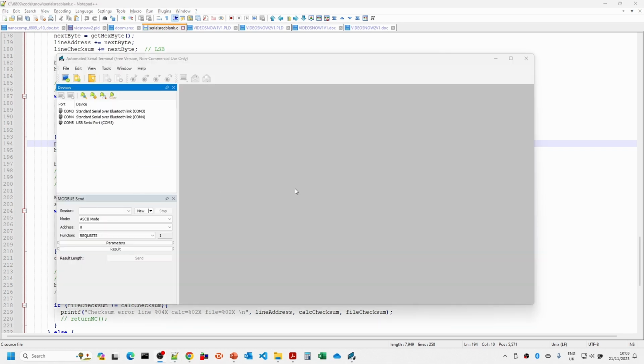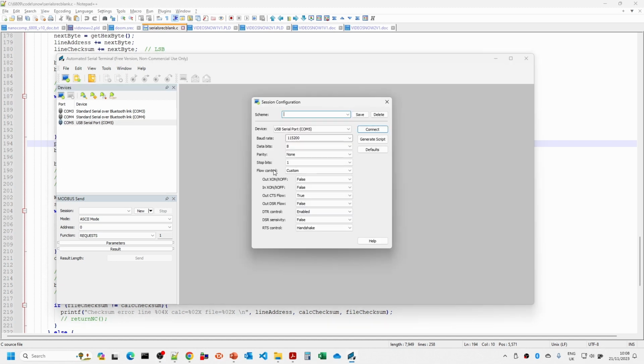So I had a few problems using the Realterm program I was using when it was doing large file transfers with the request to send, clear to send, CTS, RTS handshaking. What seemed to happen, it was using some sort of large buffer and it would time out after a certain period of time. So I'm just trying out another terminal emulator here. It isn't quite as useful for the sort of things we're doing, but I just wanted to try out a different terminal emulator.